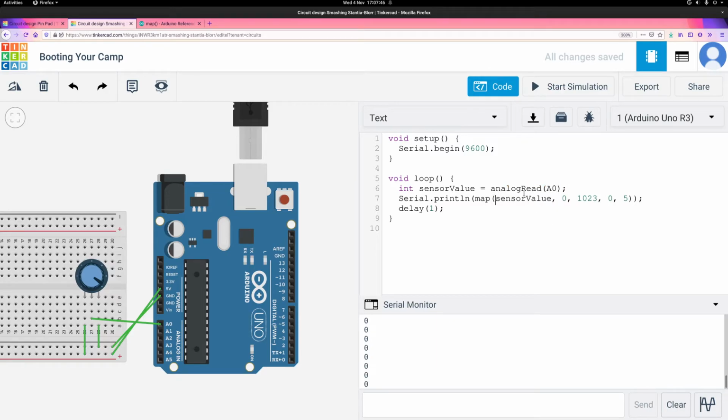This is just, I guess, the more Arduino-y way to do it, because you've been provided it, but you definitely don't need to do it that way. In fact, your way might even let you, if you convert it to a floating point number, get a decimal first. So we can give that a quick go, actually, with what you've suggested. I think by default, this will give us the exact same answer, but we might be able to do something that fixes that. So sensor value, and then we'll be multiplying by 5 and dividing by 1023.